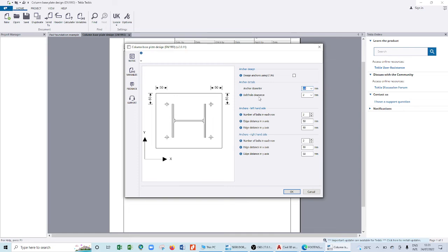At least give it some allowance. And again, you don't need to give too much allowance. Minimum, you choose 2. If you choose something like 3, then you realize that your plate, actually, the nuts itself may not work, or it can easily slide, so I can keep it low at 2. So meaning my clearance is 2 millimeter.